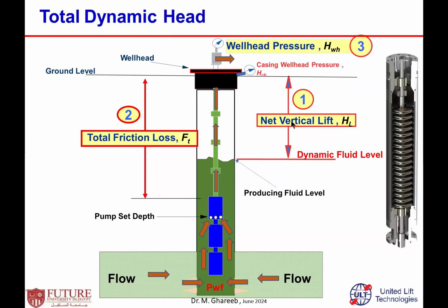Based on that, I have to calculate how many stages are required to lift that total dynamic head. To produce this total dynamic head depends, as I said, on the stage configuration and the performance of the stage and so on. Then the number of stages required for the pump to overcome the total dynamic head equals how much total dynamic head each one of these stages can produce.